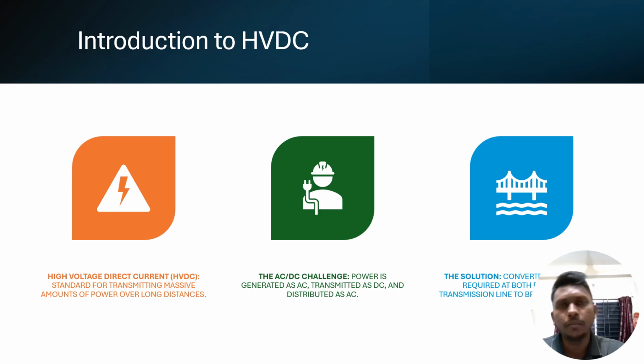And there are some limitations. The conversion is complex. SCR-based high voltage direct current requires reactive power compensation.